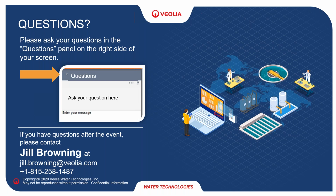Great, thank you, Mark. Another question is, is it possible to operate this process, say, on and off, for example, only in the summer or during a certain period of time, or does it need to be continuous? There are possibilities to work around. We tried with the client to work around to do seasonal operation, but you have to keep in mind that you either need to send a little side stream to make sure you keep your biology active, or you will need a startup time.